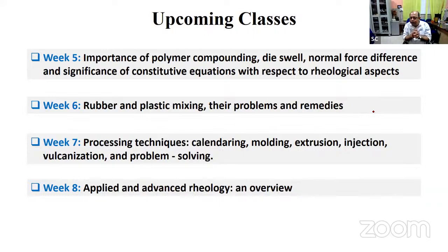Okay, die design, again taking the help of rheology, solving a constitutive equation by a computational technique. I specifically showed you a fluid mechanical technique where we used finite element techniques on top of fluid flow, basically to design a perfected die. Remember, here we consider only the die zone, that means die land to die exit, that part only.